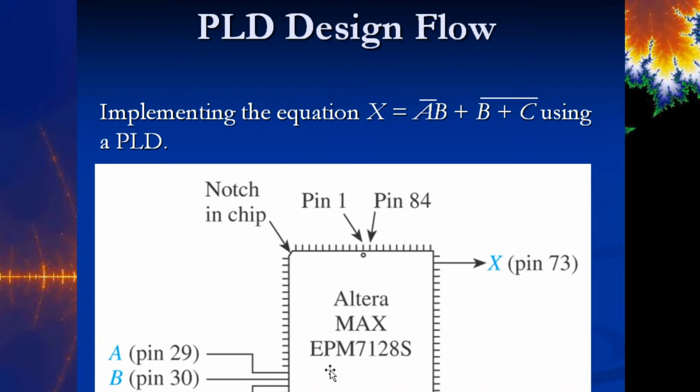Now this is an example of a different type of Altera chip, a Max, whatever this is. The way that you would orient this to know whether you have it in the right orientation of where you start counting, there's a little notch in the left-hand corner here. You would orient it so this is in the top left of how you were looking at it. More than likely, it's going to be printed on here just like this if it hasn't rubbed off, so you can see which way it should be facing. Okay? And then just like all the other IC chips, it's got a little notch that indicates where pin 1 is. And then it just goes counterclockwise all the way around.